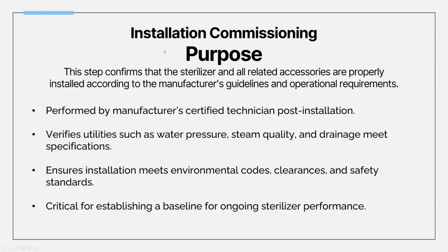So the first step is installation commissioning. It's performed by the manufacturer's certified technicians. This process validates that the sterilizer is installed as per specification. It checks utility systems like the water, steam, and drainage within the hospital infrastructure. It verifies environmental compliance, so that's clearances, ventilation, and electricals, and confirms documentation of safety and function prior to use. This is the foundation for all future validation steps.